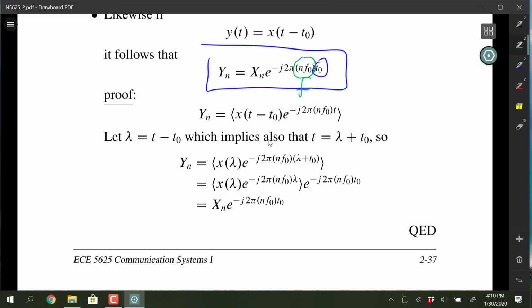Another big moral to this story is if you're looking on the spectrum analyzer and your waveform gets shifted back and forth, and you can't really control that from the function generator, the magnitude spectra is totally unimpacted by the time offset. And that's true here, because we take the magnitude and the t0 doesn't factor in.